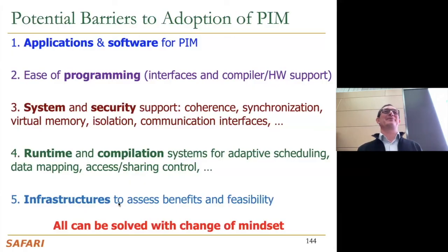Great. Fantastic talk. So I have a question. Is it possible to optimize new DRAM cell structures for processing using memory? As far as I know, in the device community, for example at the IEDM conference, some people propose to use two-transistor zero-capacitor embedded DRAM to do the math computation. Do you think this can be accepted from the industrial point of view?